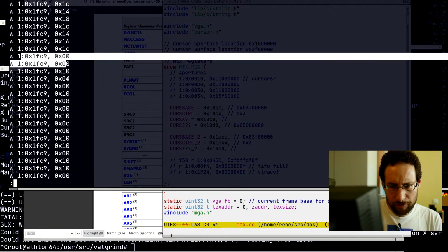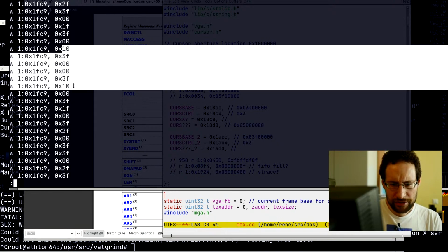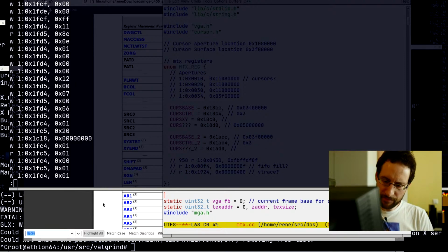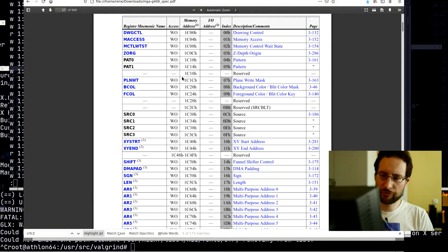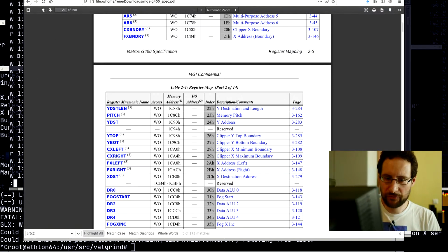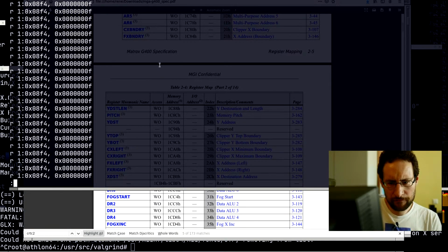It's also writing here several values multiple times into that, so this might be some indexed register of stuff we need to decipher more and maybe match to. Often you can match this if you're lucky to what they have done in previous generations, so some of the bits and registers might still apply, but maybe not. The CRT stuff looks on the first glance pretty different from the G400. But yeah, that's how you're doing it, one step at a time.